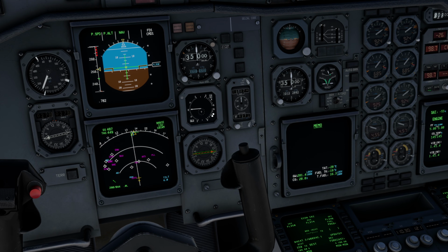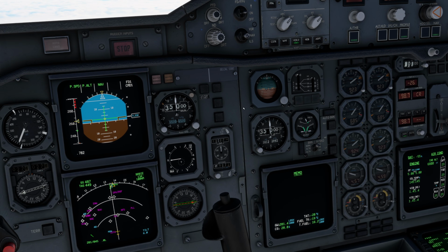Now this is going to extend the range at which we see aircraft that are below us, and that has the big advantage that we get a better picture of what's going on underneath our aircraft. Now you might be wondering, why is that important? Well, two things. First of all, when you have an emergency descent, you would be turning off your airway. So let's say a decompression happened and we would be turning 45 degrees off, either to the left or to the right. If we've got our TCAS in the below mode, as indicated by the below sign down here, that basically tells us that we can get a better picture of what is happening beneath our airplane.